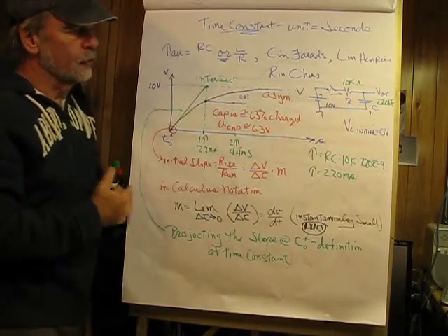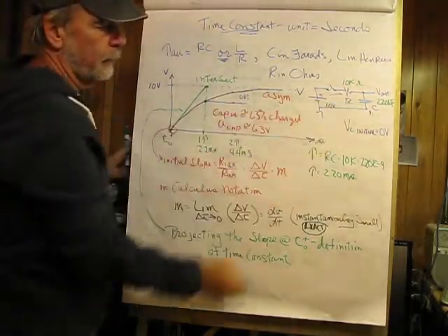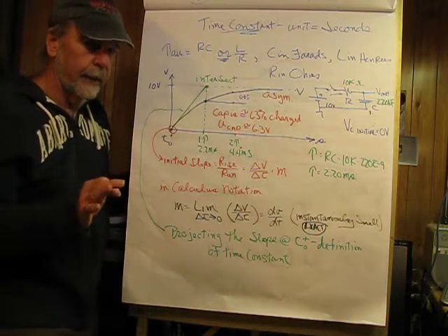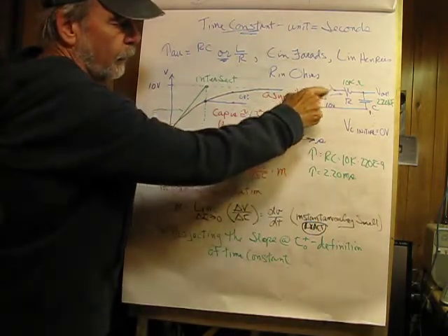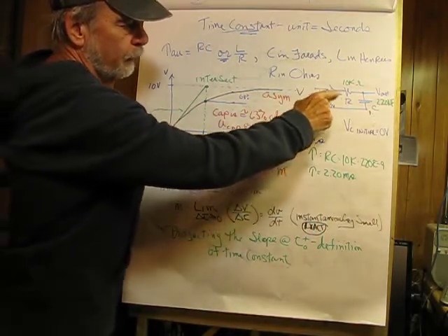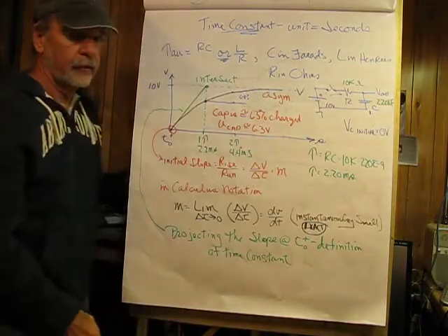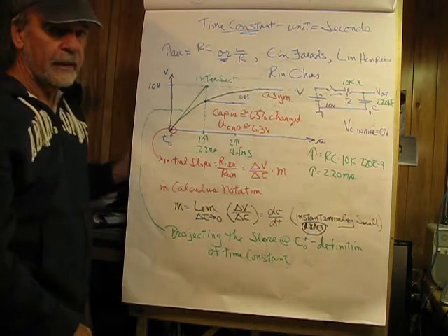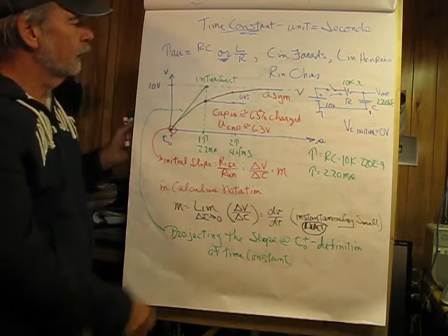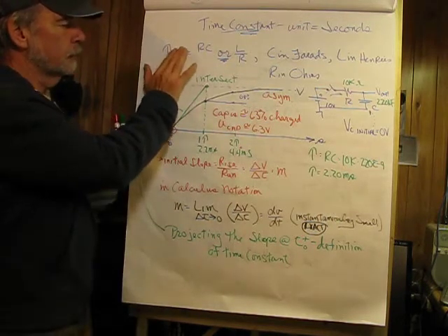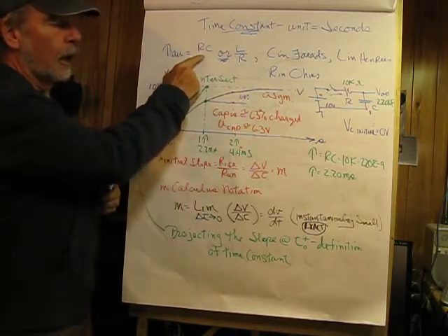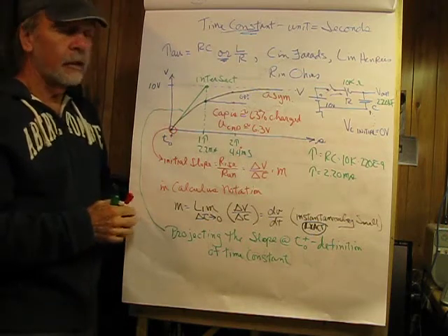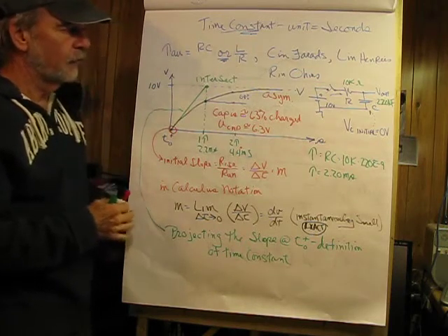So this is the situation here: we're starting out with the capacitor voltage equaling 0 volts, and you absolutely must be told that. We're going to close the switch here, and when we do that, we're going to have current that's going to charge the capacitor, and the time it takes to do that is referred to as the time constant. Now, the time constant, tau, in an RC circuit is equal to R times C, and if we have an LR circuit, it would be equal to L divided by R.